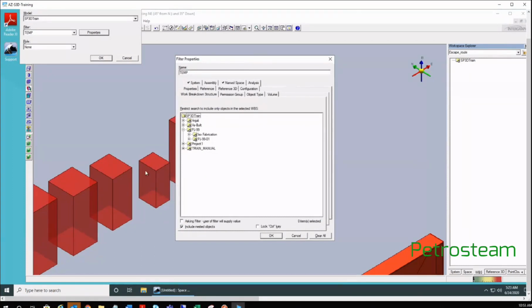After that, overnight when the rule checker process runs, it will check for the new pipelines modeled today and then assign the volume name for it. Once the volume name is assigned, the backend rule checker process will automatically create a WBS item for this piping. It will create an isometric WBS here and then assign all the objects. They are piping parts actually. The assignment is by piping part.